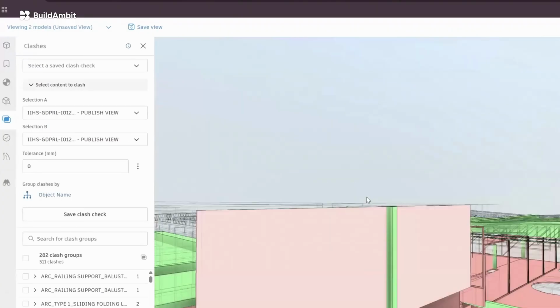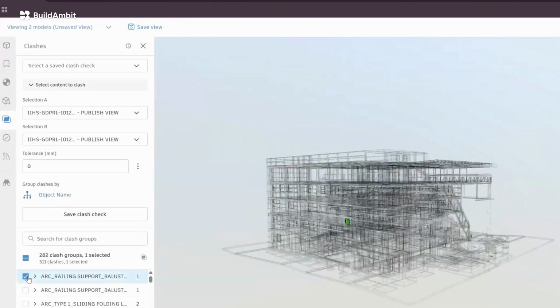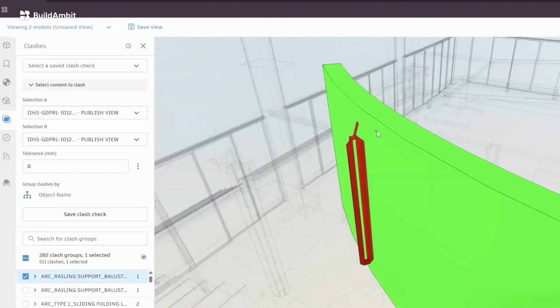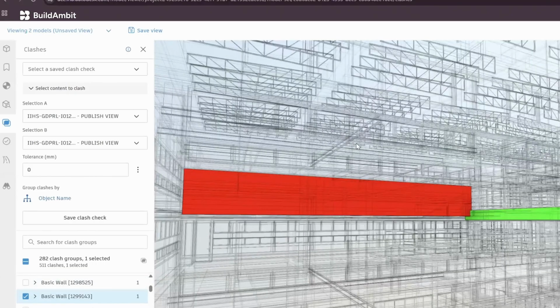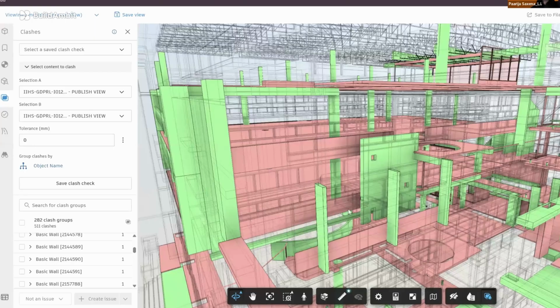Now here's where BIM stops being just a fancy 3D model and starts actually touching money and time. This is 4D and 5D BIM. 4D ties the model to your construction schedule, so you can literally watch the project get built sequence by sequence before a single brick is laid. 5D takes it one step further and connects quantities in the model directly to cost. So the moment the design changes, the budget updates itself. Nobody is sitting there manually recalculating. And this is also where quantity takeoff happens, pulling exact material quantities straight out of the model instead of someone counting them off a drawing by hand.